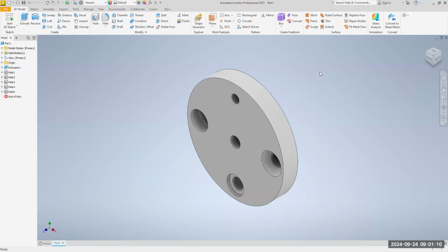Well, you can also eliminate burrs and rough slivers of metal. The reason why is we always want to practice good safety processes, right? We want to make sure that a person who is going to handle this part is not going to get a metal sliver, and they hurt a lot. I know. Okay, so go to chamfer. We're going to put a beveled edge on this edge and this one, and we would do this on the lathe. Okay, so select chamfer,